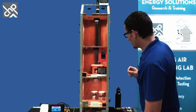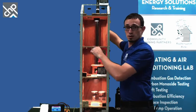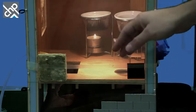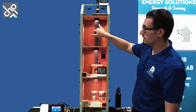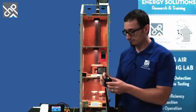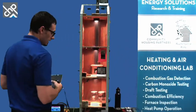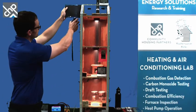So what I'm going to look at now is what happens to that smoke if I create an opening inside of my attic here. I'm going to open this attic access. Immediately, what's happening with the smoke? Smoke is now rising up, and it's actually rising up through the structure all the way into the attic. I can see it around this light now, the smoke. And then if I come over here, I've got a little flashlight and a little background material so we can see what's going on. So we may not even need this additional smoker. You guys might be able to see what's going on.